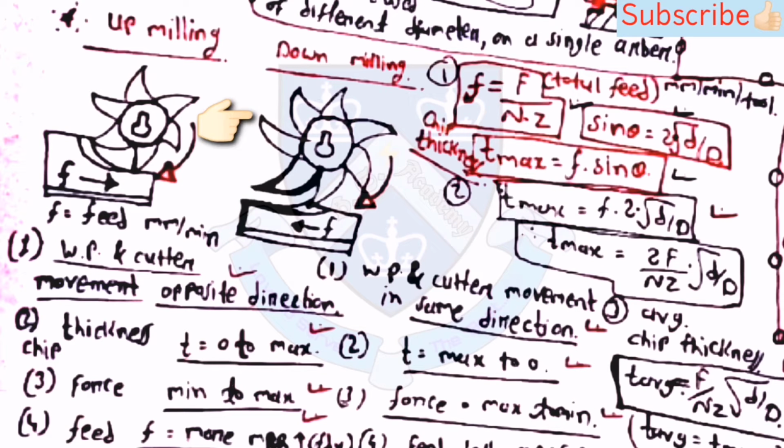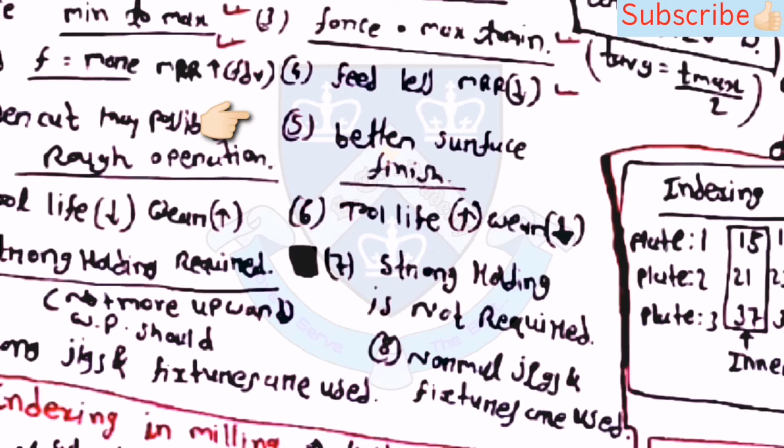Then in the down milling process, the workpiece and the cutter movement are in the same direction. T is from maximum to 0, and the force is from maximum to minimum. Feed is less and MRR will also be lesser. Then there is better surface finish, tool life will be higher and wear is lower. Strong holding is not required and normal jigs and fixtures are used in this process.